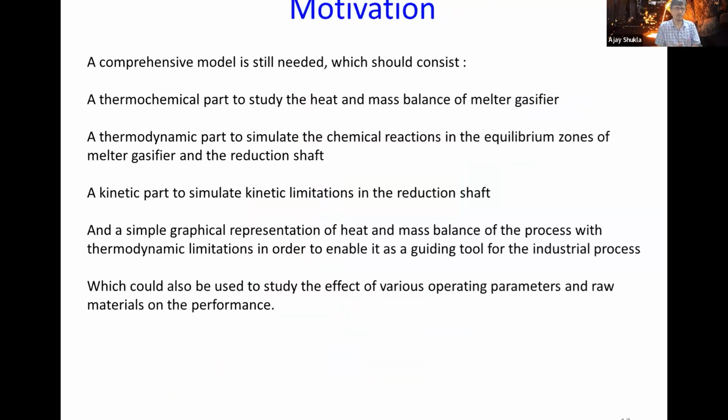So basically our motivation was to develop a comprehensive model where the thermochemical part of the study, the heat and mass balance, was performed. So a static model was developed. And then the thermodynamic part simulated the chemical reactions in the equilibrium zone of the melter gasifier and reduction shaft. So the kinetic part was to simulate kinetic limitations in the reduction shaft.